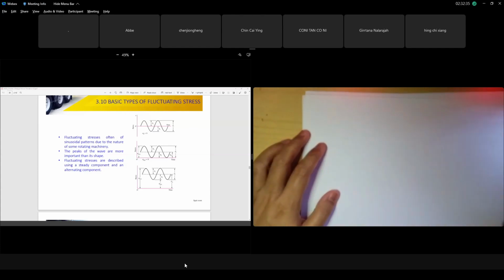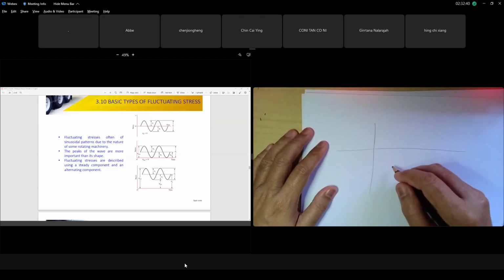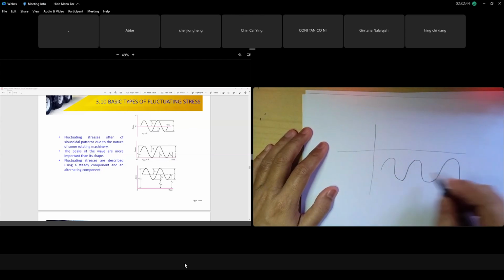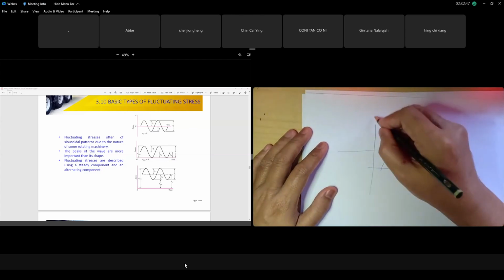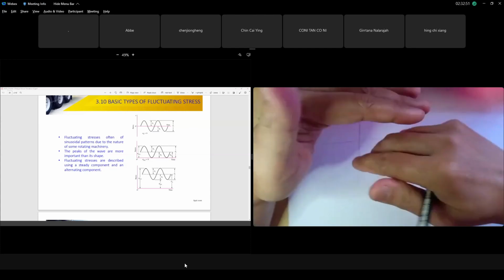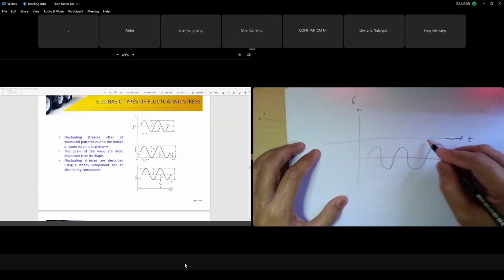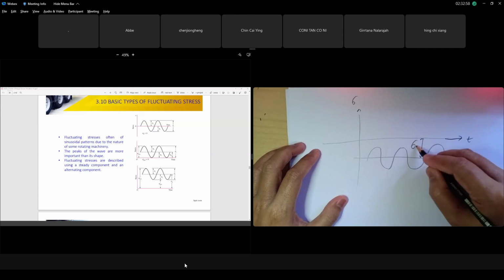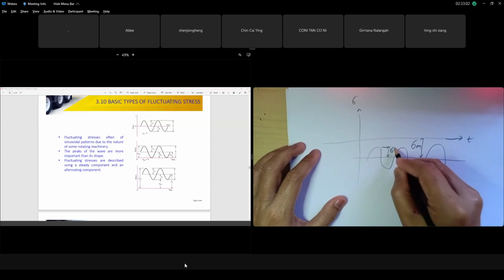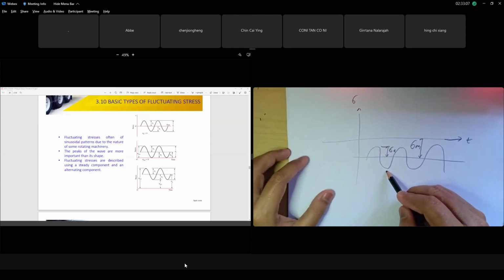if your mean is negative, it means your case is all in compression mode. In a case like this, it means your case is all on the negative side. Your sigma, either bending through time, goes negative. It means your loading is always applied in compression, negative stress. So this is your sigma mean. In this case, your sigma mean goes negative, but your sigma amplitude is always positive, because sigma amplitude is max minus min divided by 2.